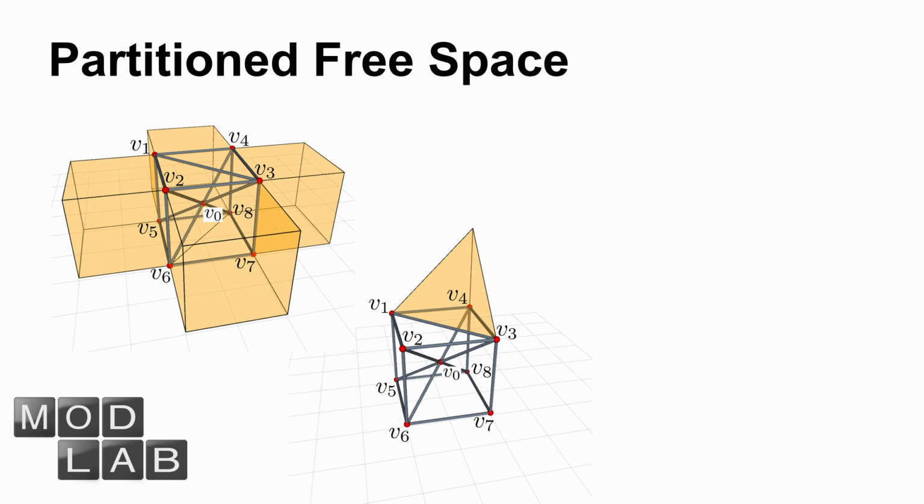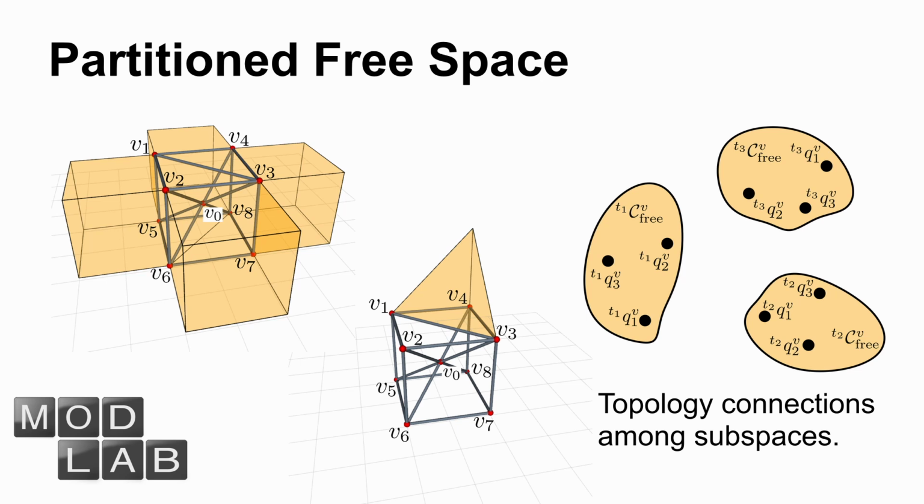Topology reconfiguration actions are highly affected by the node position, and a routine is created to generate as many samples as possible to span the enclosed subspace along with valid topology actions. Two transition models are built to connect two adjacent enclosed subspaces, and a graph search algorithm can be applied to compute a sequence of topology reconfiguration actions efficiently.